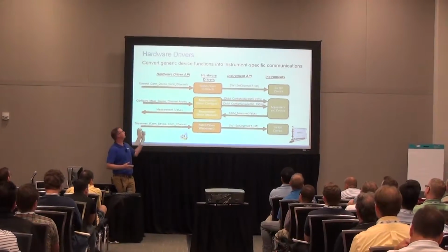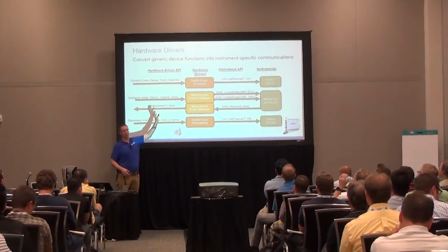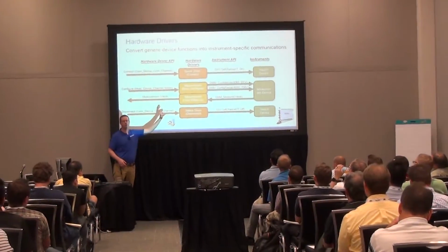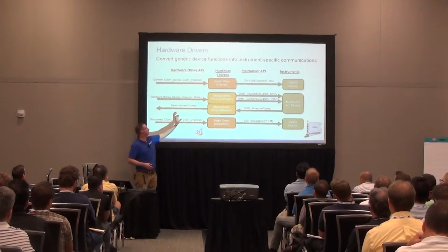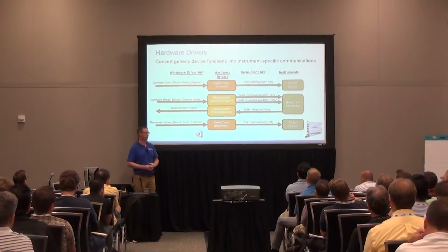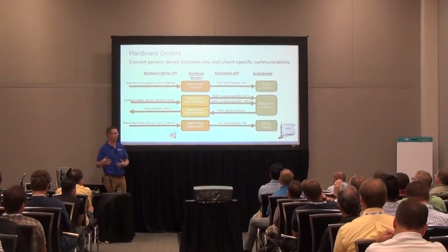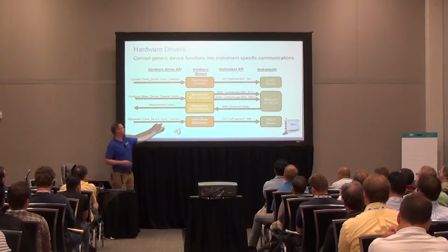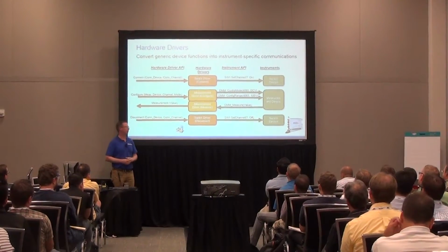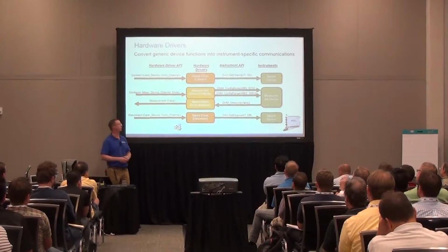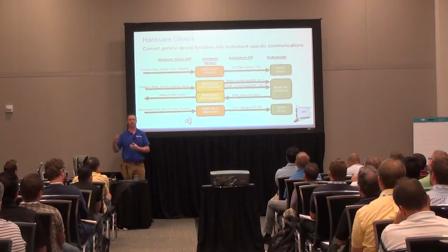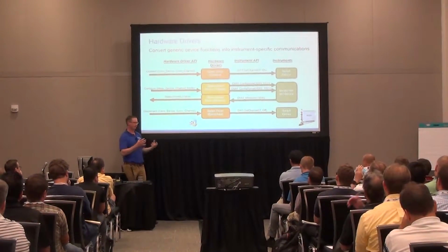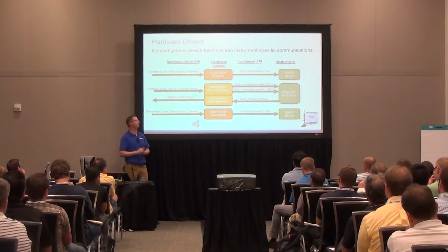So as we propagate it farther, we pass that information to our switch driver. This is in our hardware abstraction layer. We pass the measurement device and mode and channel to our measurement driver. So we may have a driver for our particular DMM in this case. We then call the measure function from our DMM, and then we call the disconnect from our switch. Each one of these drivers could be a packed project library or a LabVIEW project or a DLL that has all of the functions necessary for it.